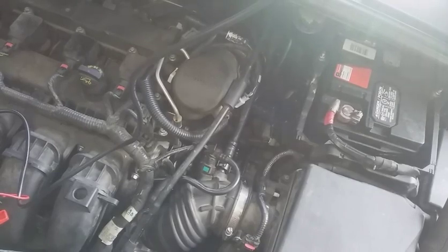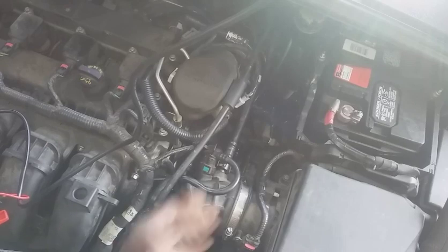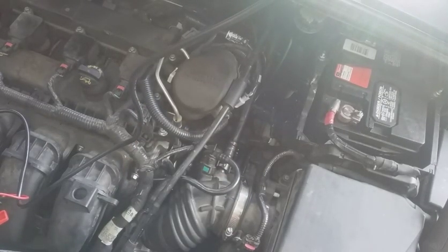It depends on a few various conditions what the manufacturer recommends. But she left, and it stalled when she got to a light. This explains why. This is a common symptom. It could generate a vacuum leak, and it would also cause these rich conditions, which she was experiencing a while ago when I initially scanned the vehicle for codes.